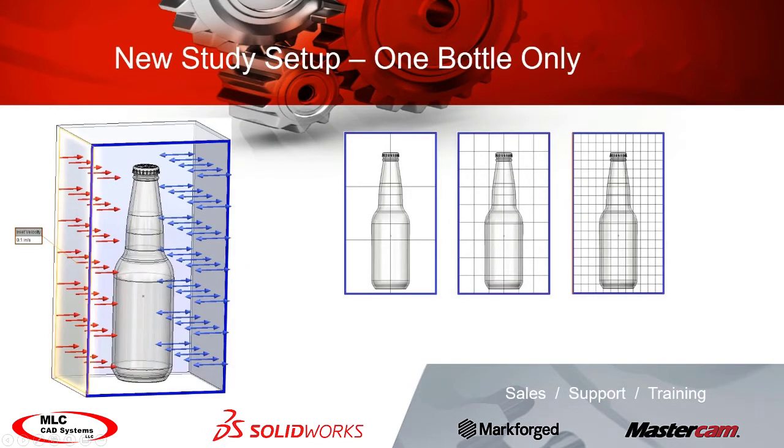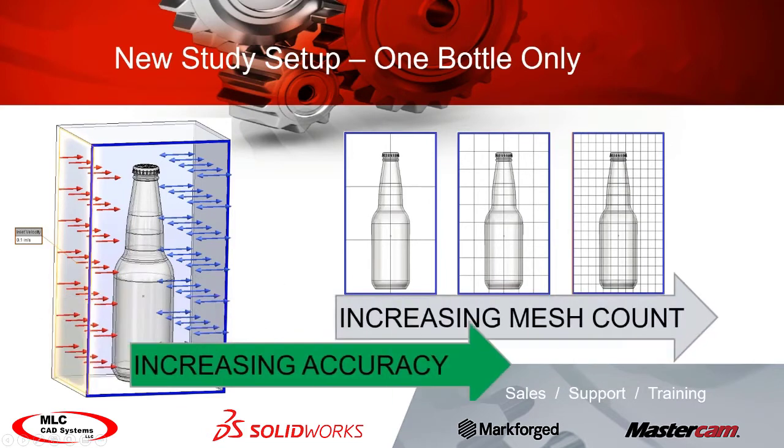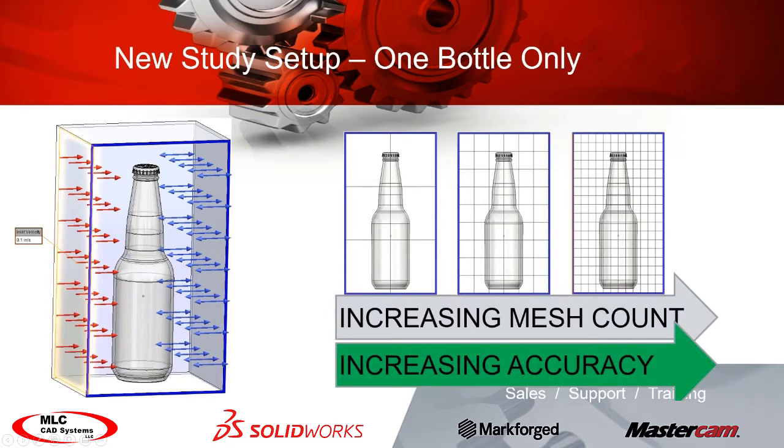To simplify things down and really focus in on the new problem statement, because I'm starting my second loop here, the new problem statement is, what kind of mesh density do I need in order to get an accurate solution? And as you see on the left, the setup is just going to be air blowing over this thing, and I start out with basically 6 very big elements and then refine it and refine it and refine it. As the mesh count gets higher, the accuracy will generally get higher, but the solve time goes up.